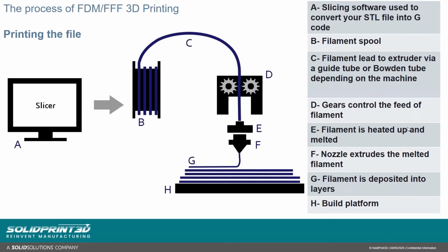If you give your models a nice flat base, it's going to give it the ability to lay it down and build up that first layer of extrusion correctly. Usually the most important steps of the process with 3D printing is the first few layers. If you know they're adhering, if you know they're going down nicely, and as long as we design for it, it's only going to ensure that you're getting the best out of the print process itself.